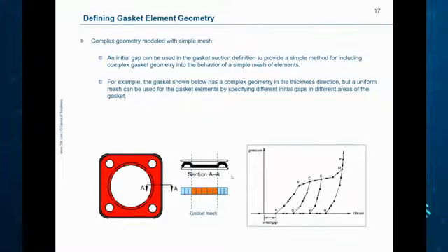And the pressure closure definitions in Abaqus allow us to account for the complex mechanical response in the thickness direction, including the effect of the gap. And because the middle of the gasket cross-section is different than the bumps, we have to have different behaviors defined to account for the bumps in this case, and then the gap in the middle.